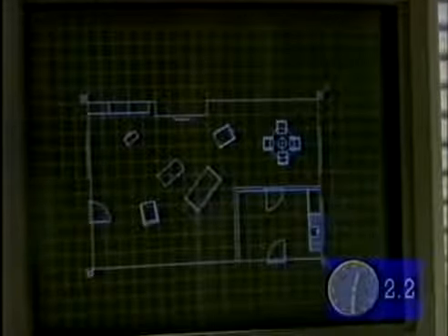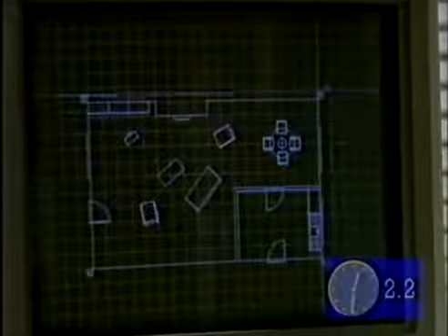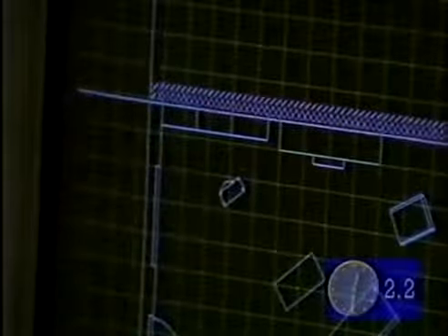So again, selecting it from the menu, all I need to do now is point to one of the corners, like so, and it snaps to that symbol, and then the other side of the symbol. Again, this symbol is a kind of elastic symbol whose length is defined by those two points, these two kinds of positions to make a continuous run of brick wall.